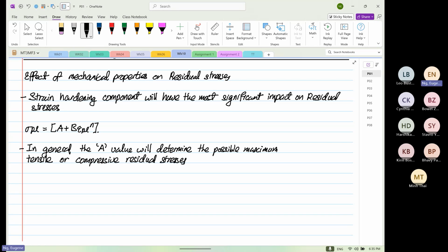Okay. In general, your residual stress maximum, this means absolute value, either compression or tensile, is usually less than 1.1 multiplied by your A value. Okay. If it's greater than that, be very suspicious. And I'll highlight a case study or a consulting work where no one had a clue what they were measuring, and they paid a lot of money to get a ridiculous value, which is wrong. Okay, and then we got it right.